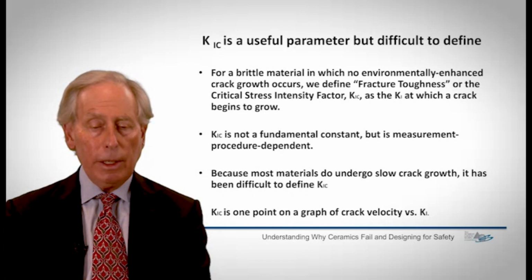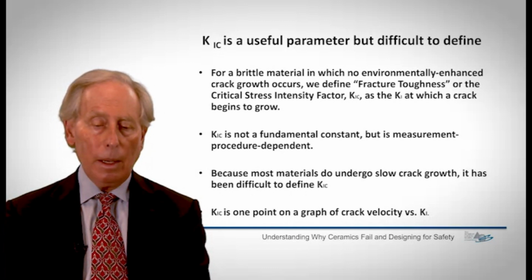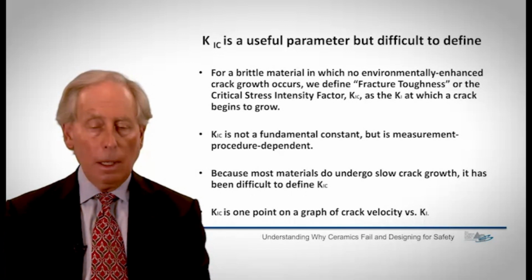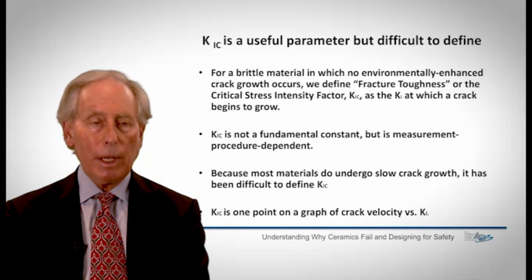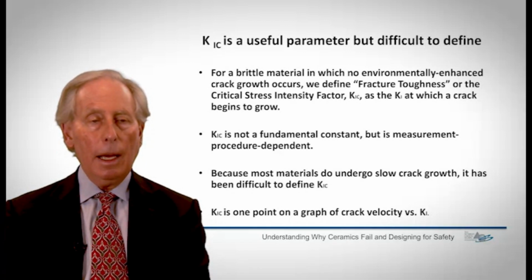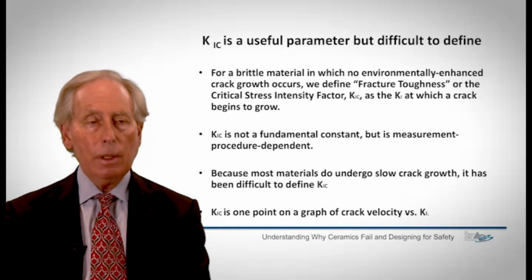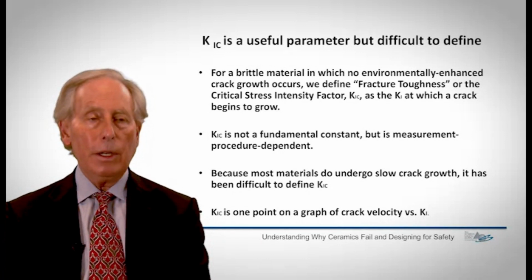So for a brittle material in which no environmentally enhanced crack growth occurs, I say we, but others too, define fracture toughness, or that critical stress intensity factor, as the stress intensity factor at which a crack begins to grow. And there's still argument in the literature over whether that's the right definition, but I think it's a useful definition for at least we who are doing engineering work with these materials.